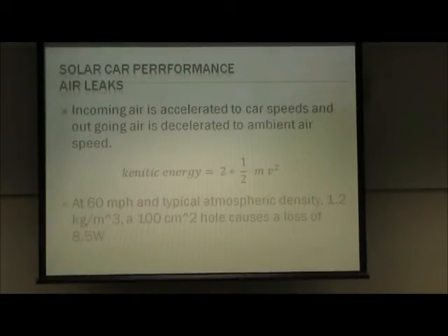Solar car performance, air leaks. Suppose you have air leaking into the car: a hole in the front, holes in the wheel wells where it comes in the front and goes out the back. Ventilation even. Any air in and out. What happens? There are other turbulence questions too, but one big loss is that you have to take that mass of air coming in, let's assume it's at 0 miles an hour, and speed it up to the car speed. You have to accelerate it.